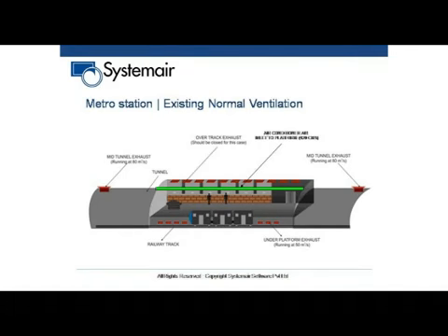There was this under platform exhaust which provided 50 CMS. There was a mid tunnel exhaust between both the connecting tunnels, extracting air at 80 CMS. Air conditioned air was supplied from the platform at 120 CMS, and the overtrack exhaust was actually not operating at that point. We installed the overtrack exhaust, and in normal operation it was not working. So this was the existing system.